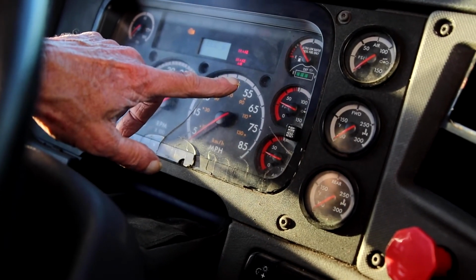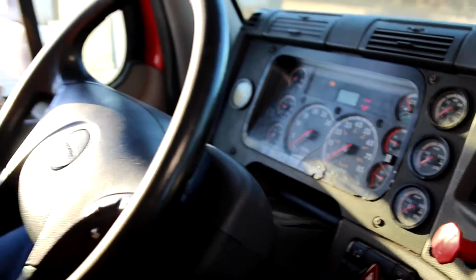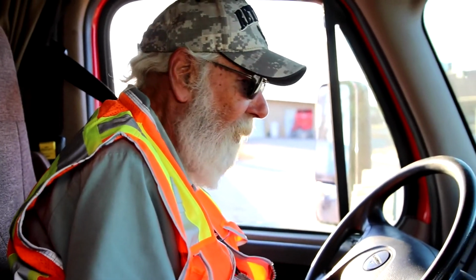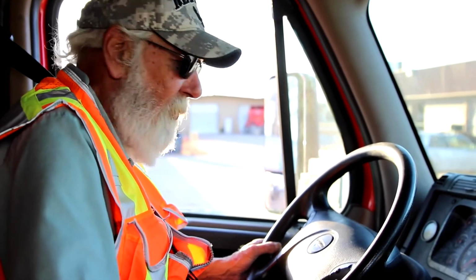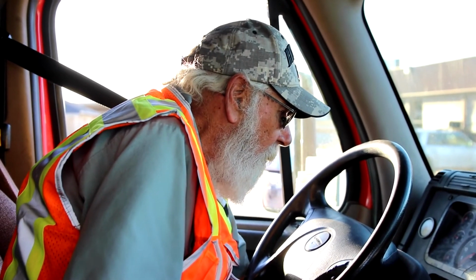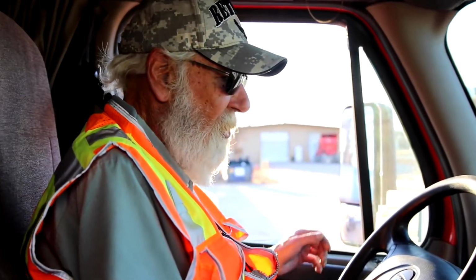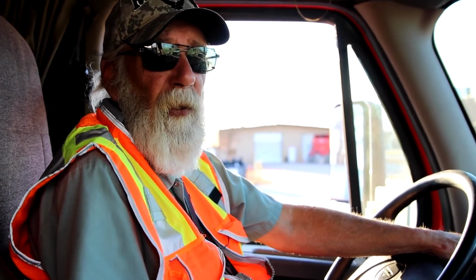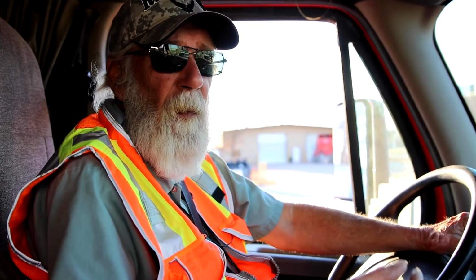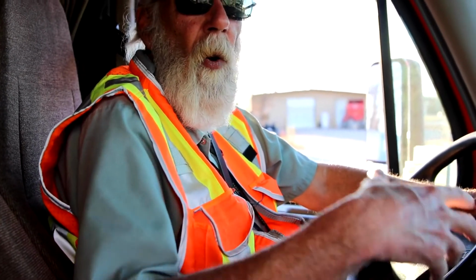So I'm within specifications. The next part of my test is I'm going to do another safe start to build my air pressure back up. So again, clutch to the floor, transmission in neutral, restart your engine. Gently off the clutch. I'm going to rev my engine between 1100 and 1400 RPMs to speed up my compressor, and between 120 and 140 pounds, my governor will turn my compressor off. You will hear a ka-ch, or as some people call it, a sneeze.